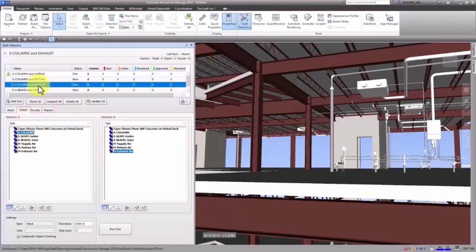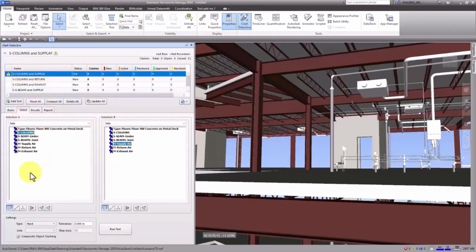Now I select this first item and here in select. As I told you before, when I select, they will change. Here in this section, we have some tools for selection A and selection B, each one separated. Here we have surface. Here we can choose to have clash for surfaces or not. And for sure, we want this. This is our purpose. We want to find it out. Next one is line. Do we want to know about the clash in lines or not? Normally, we don't need this except for the times when you have some models with lines, which can help you in clashing.